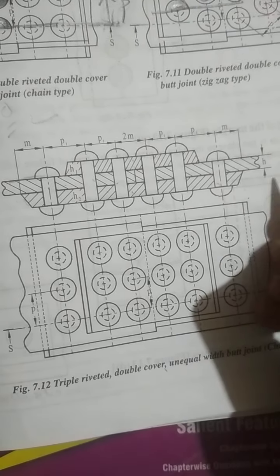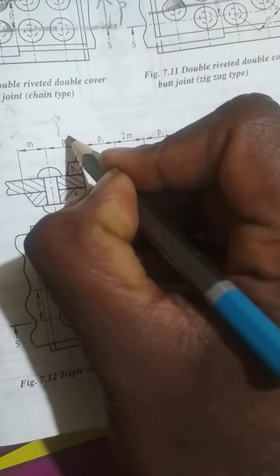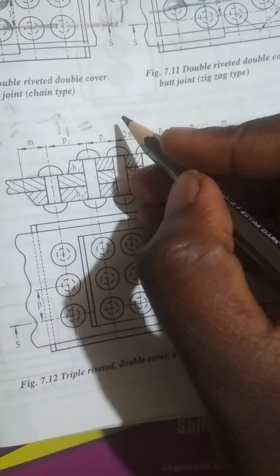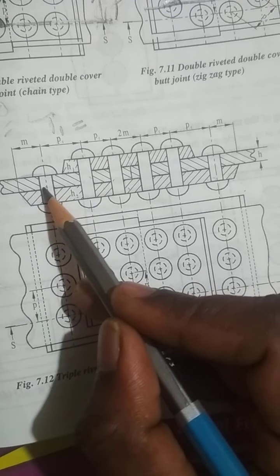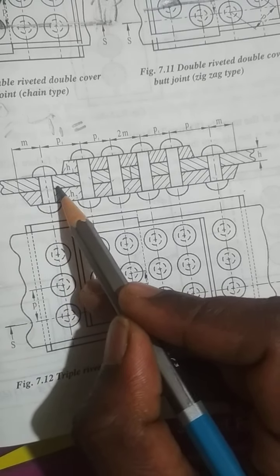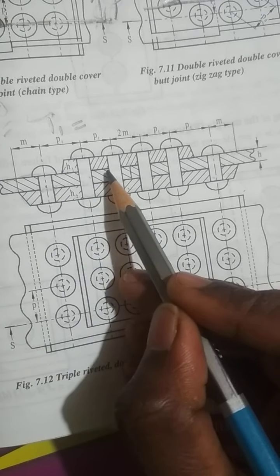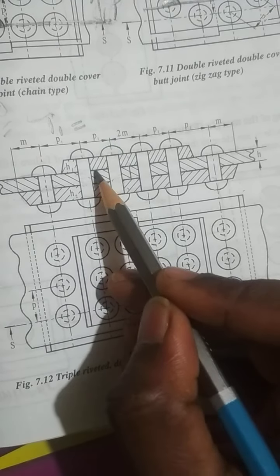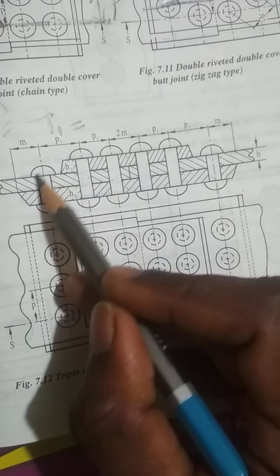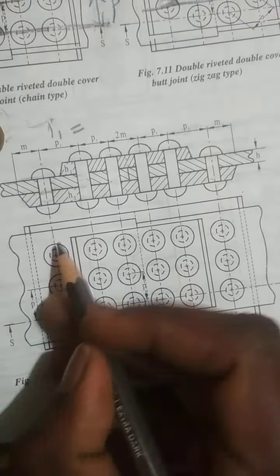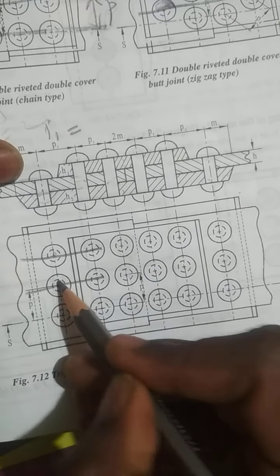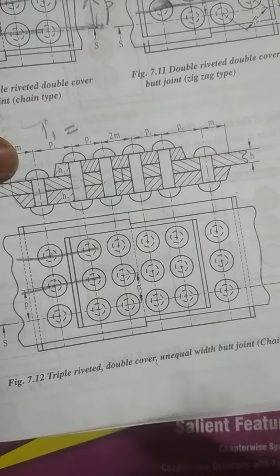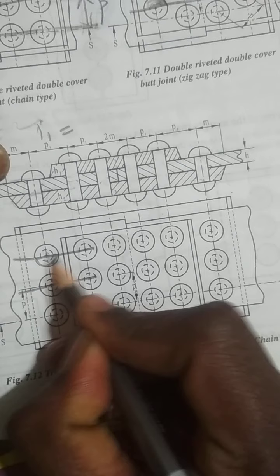Then we have to find out I1 and I2. I1 is equal to the number of rivets in single shear. Consider one plate. First, you can see that in the first row of rivets, there is single shear. Here these 2 rivets are in double shear. Then for the I1 case, we can consider this one. Considering the pitch length, these are the pitch length. You can take either these 2 or these 2. I have considered these 2. Then I will mark it down.